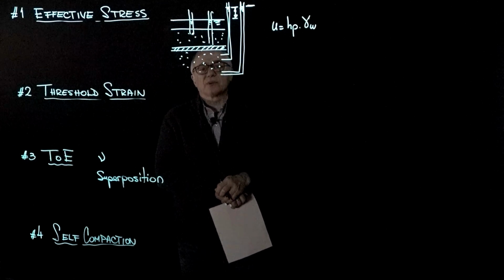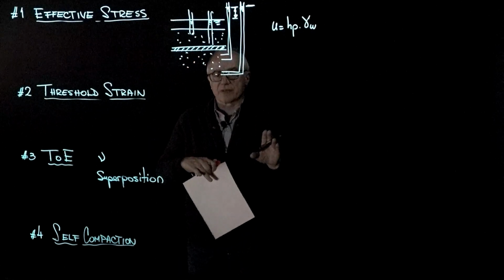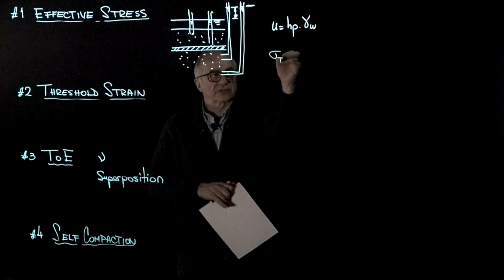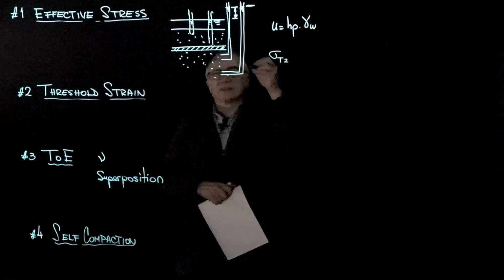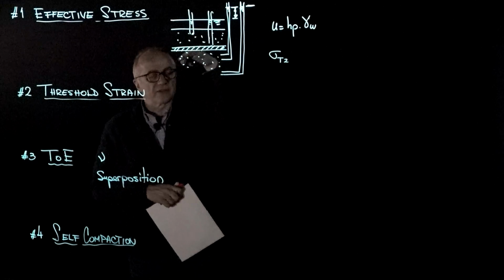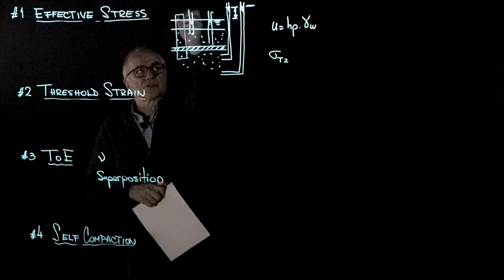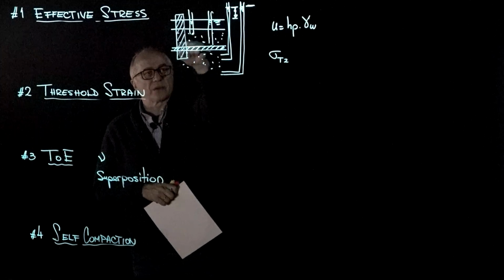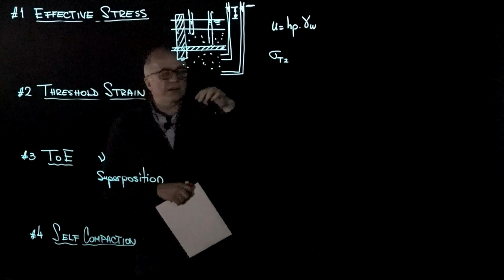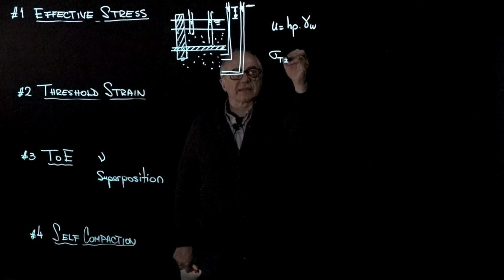So with this situation in mind, the only thing that you have to recognize, now that you know the pore pressure everywhere, is you need to know the total stress in the z direction at every point. And the total stress is computed, in this level ground condition, by adding the weight of everything above the point. So it will be the weight of the water, the weight of the saturated sediment, the weight of the aquitard, and the weight of the lower sediment all the way up to the point. So the weight of everything above the point per unit area gives you the total stress at depth z.